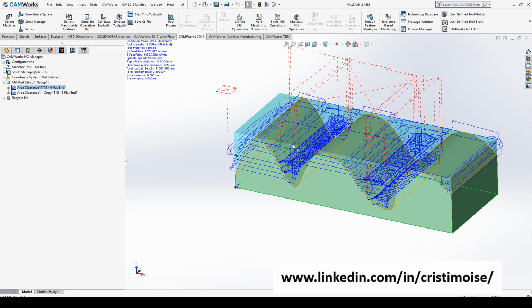I just want to switch back to 2.5 axis enhancements. Right now, you have the ability to use long code for point-to-point operation. This is directly related to the post processor, of course. So in previous versions of CAMWorks, for all point-to-point operations like drill, center drill, ream, and so on, the G code was output using canned cycles. So there was no option in the CAMWorks user interface to output the G code without the canned cycles.